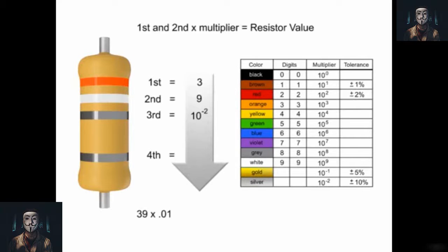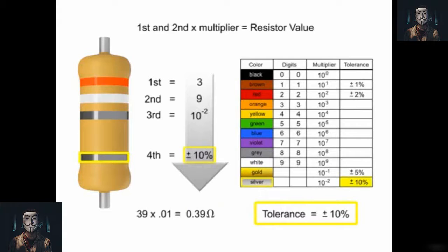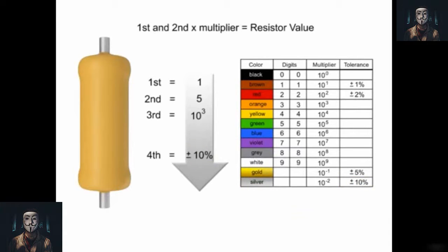A potentiometer is a 3-wire variable resistor that acts as a voltage divider to produce a continuously variable output signal proportional to a mechanical position. When a potentiometer is installed in the circuit, one terminal is connected to a power source at one end of the resistor. The second wire is connected to the opposite end of the resistor and is the ground return path.